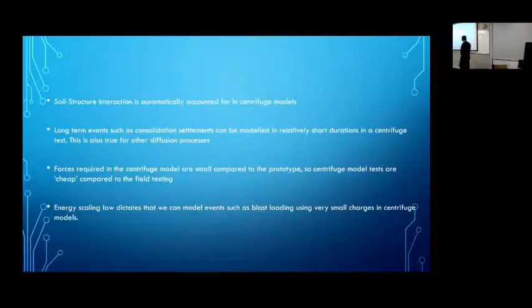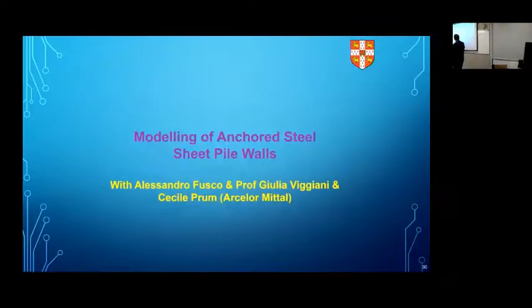Also, it is possible to test where real scale events are impossible to model. I work predominantly in earthquake engineering. I cannot wish an earthquake on anybody. And even if I wish, it's not going to happen when I want it to happen. So for studying problems like that, same with the blast events, you can use centrifuge tests to create these unexpected extreme loads onto the structure and see if it works, cyclic loads.